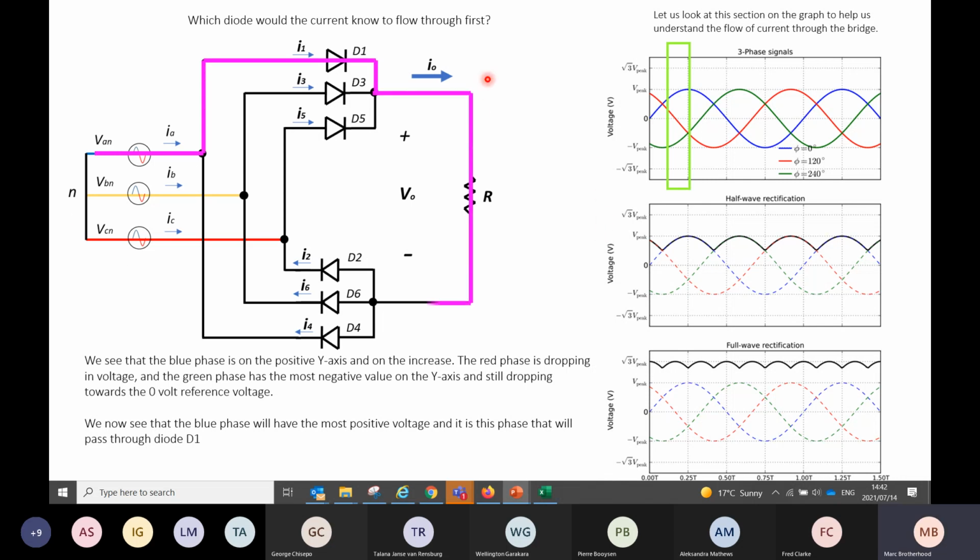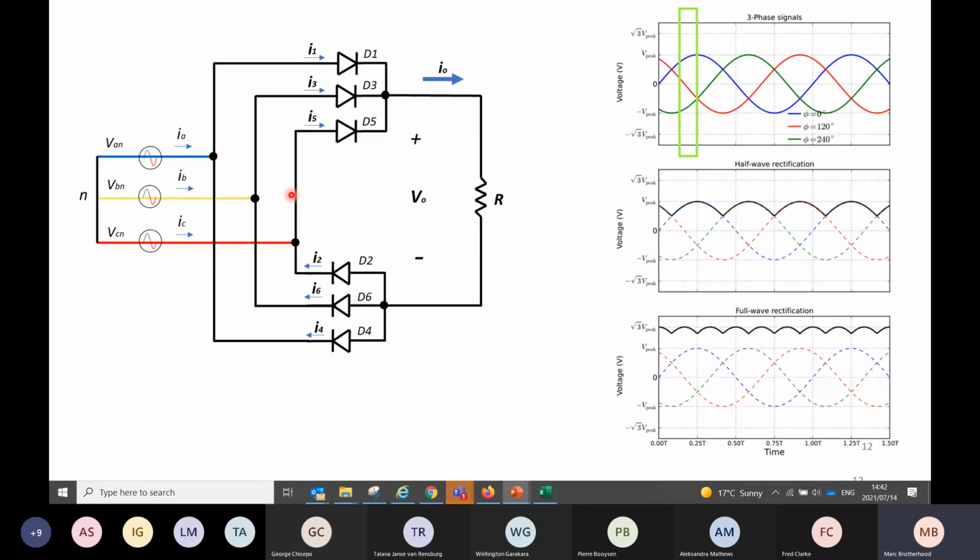and because of this graph, it's going to go through that diode first, through the load, and now it comes to voltage to D6. Now it has to decide which diode to go through. It can't just choose any path, because you're going to have a big explosion on the front end. I'll redraw this animation, and we're going to come to D6.